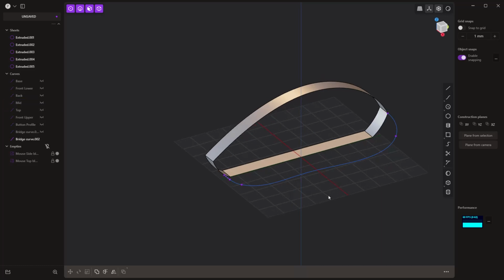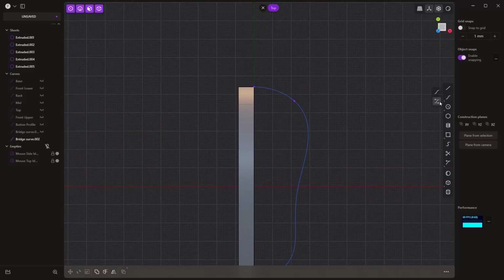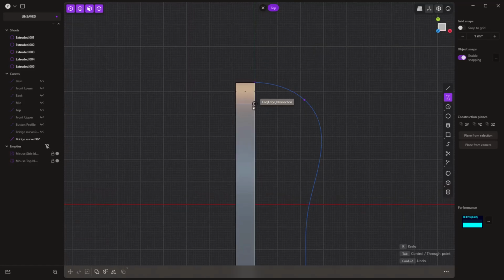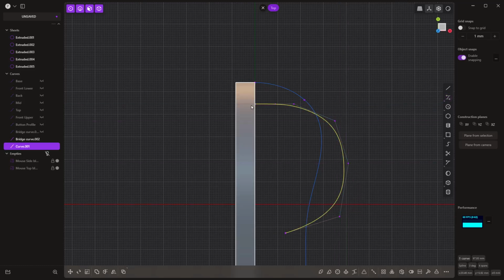There are other ways that we could do this. If you really wanted to, you could drive tangency with things like lines. I'll just go ahead and show you real quick. If you are using, let's say, the control point curve, and we tap shift, we've got this projection here, then basically what this is going to do is drive tangency, just for the fact that we brought those control points out.